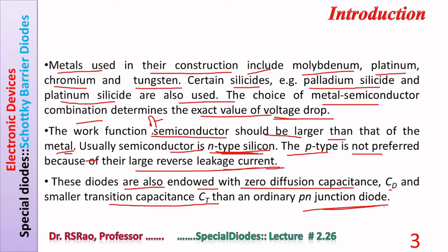diode. Notice that the existence of capacitance inside a diode limits the maximum frequency of operation. It limits bandwidth. It introduces sluggishness into the operation of the diode. Lower capacitance means higher frequency of operation and greater bandwidth.